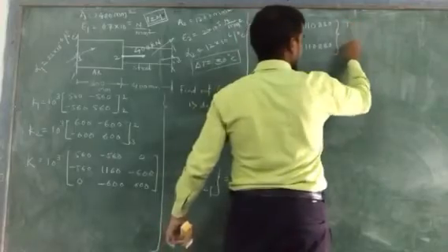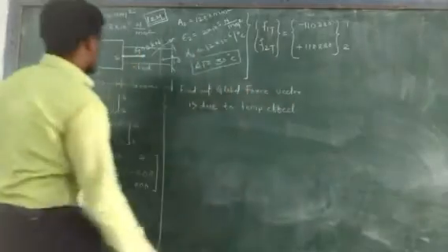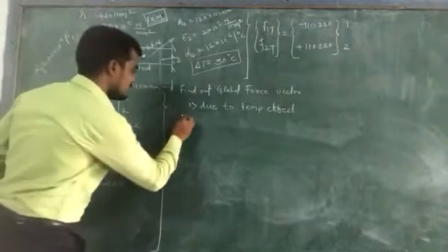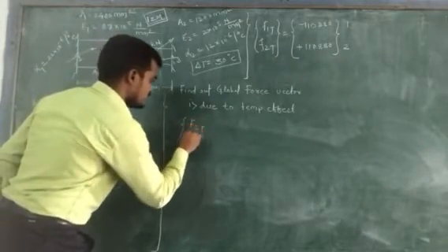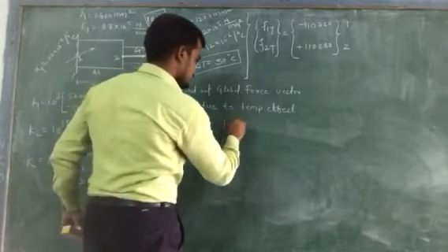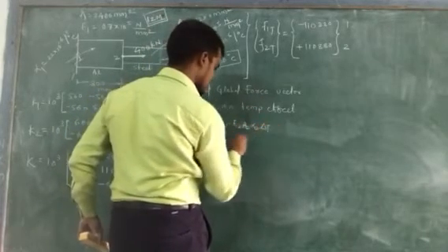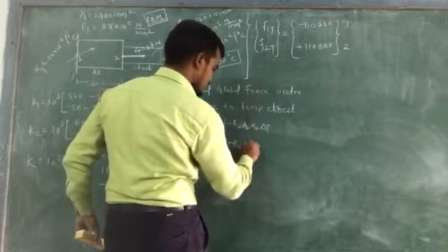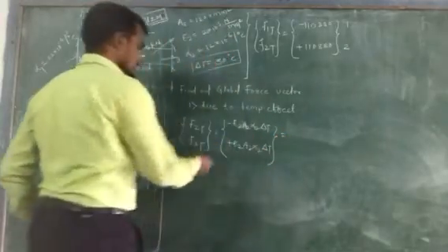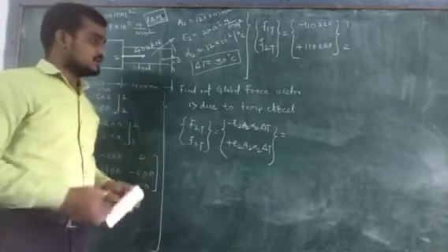This is between equation 1 and now next find out the nodal force vector due to temperature effect for this second element. So for second element it will become F2T, F3T. The same procedure: minus E2 A2 alpha 2 delta T plus E2 A2 alpha 2 delta T.